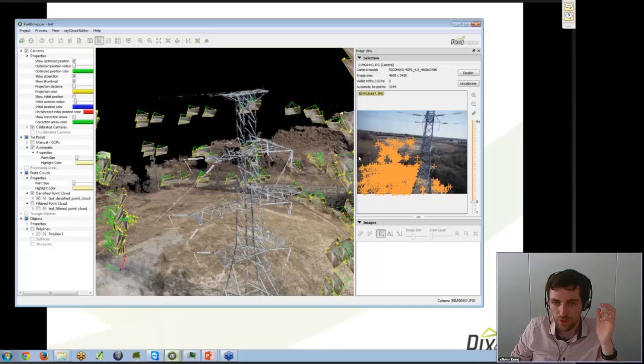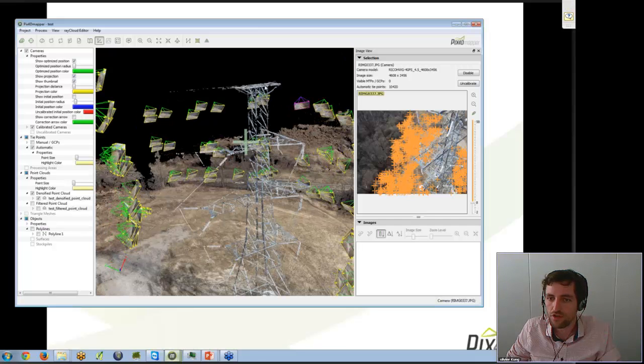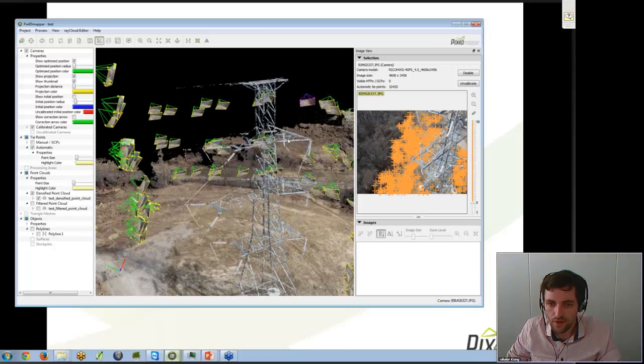So one trick is always to keep images facing a little bit more down, so the software can use the ground to compute features too, and not just the content of the tower, the object you are trying to reconstruct in the middle.